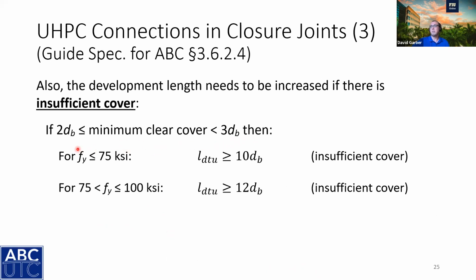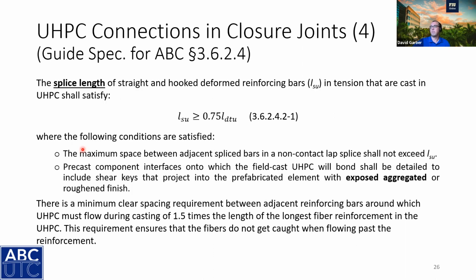If you don't meet the minimum cover requirements so that you can get all the fiber orientation that you need around the bars, then you need to increase your development length. And here the splice length is a portion of the development length.